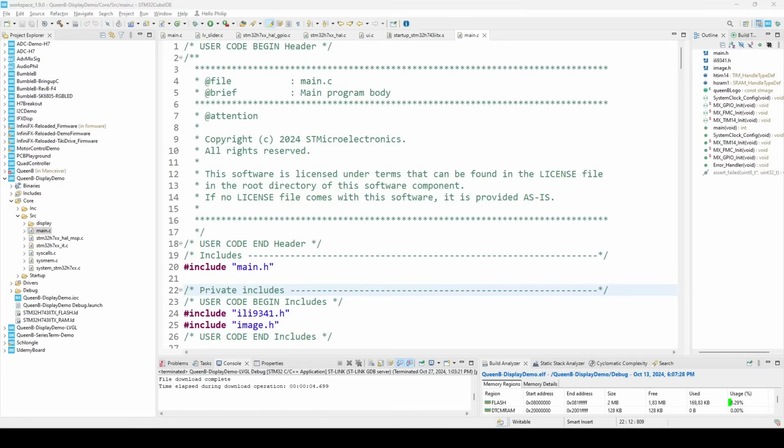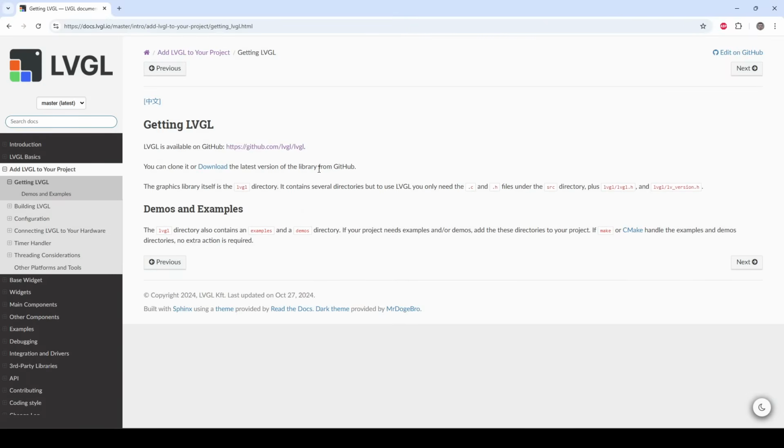We are starting where we left off with video number 146 on the channel, and again I'd strongly encourage you to check that out so you make sure where we are currently at, as I won't be describing that anymore. Essentially, all we've done is connected up the FMC of the STM32H7, as well as tested out the driver for the ILI9341, and we've verified our display connectivity to be working, and then we take this as our baseline for our project now. The first step, what we need to do, is of course download the LVGL source files or the libraries.